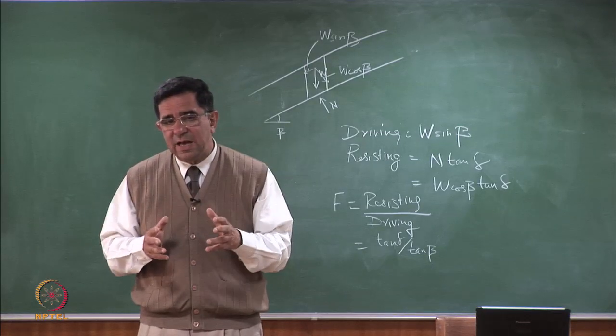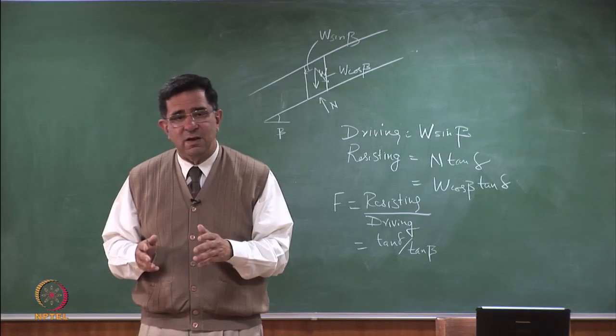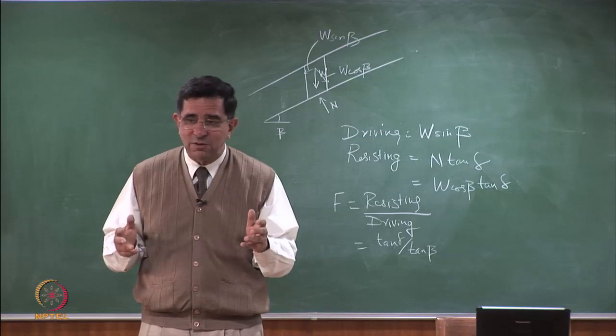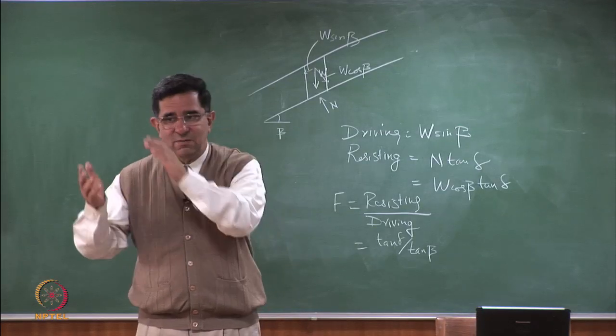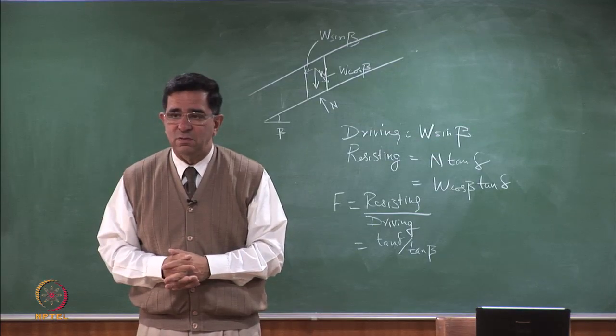So most of the analysis is like soils, except for the interfaces, which is like failure parallel to the outer slopes. And in that, now you'll start to get two-wedge also. We've just done an infinite slope analysis, but you can have a two-wedge and a three-wedge method also.